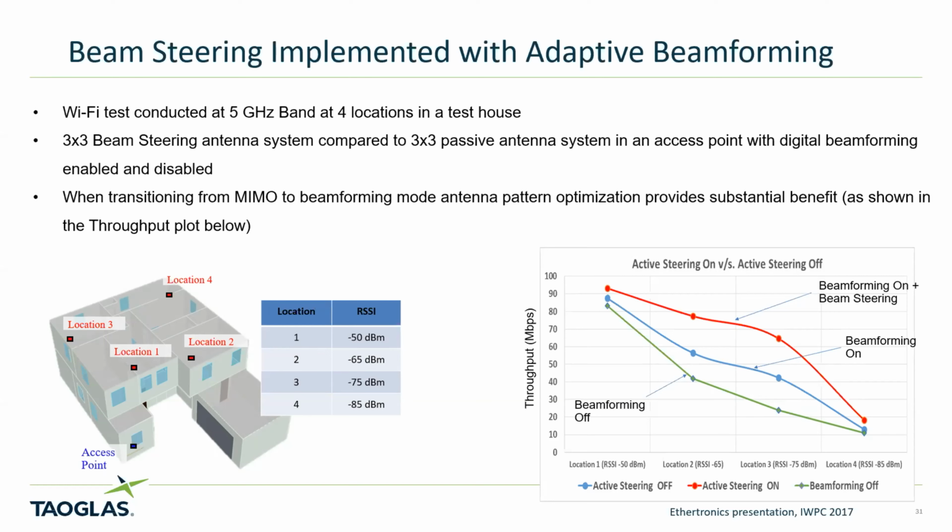Again, in a smartphone, the isolation requirements or specs are not as stringent as we find, like in the slide we're looking at here. This is an access point in your house, where it's a larger volume device. You'll wind up with 15 to 20 dB isolation between the antennas. In fact, typically a solid 20 dB isolation between the antennas. In a smartphone, we're happy to get 10 dB at the lower sub 1 gigahertz, and then you might see 12 to 18 dB at the higher bands.